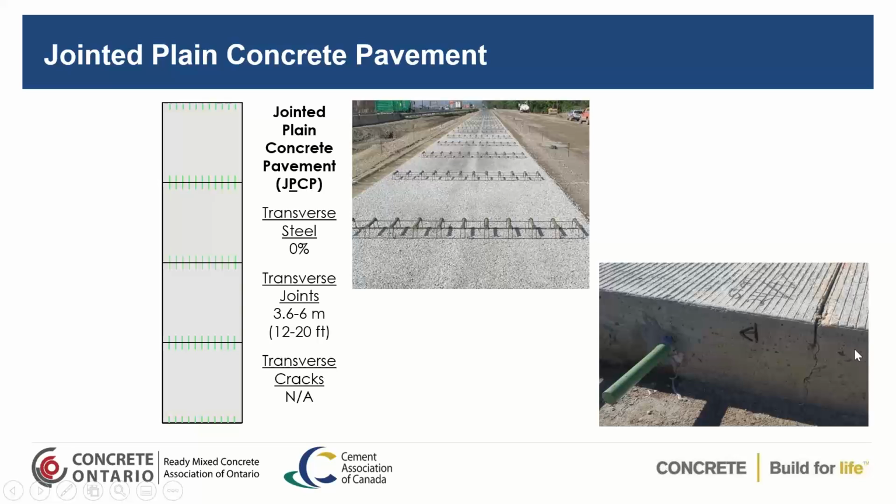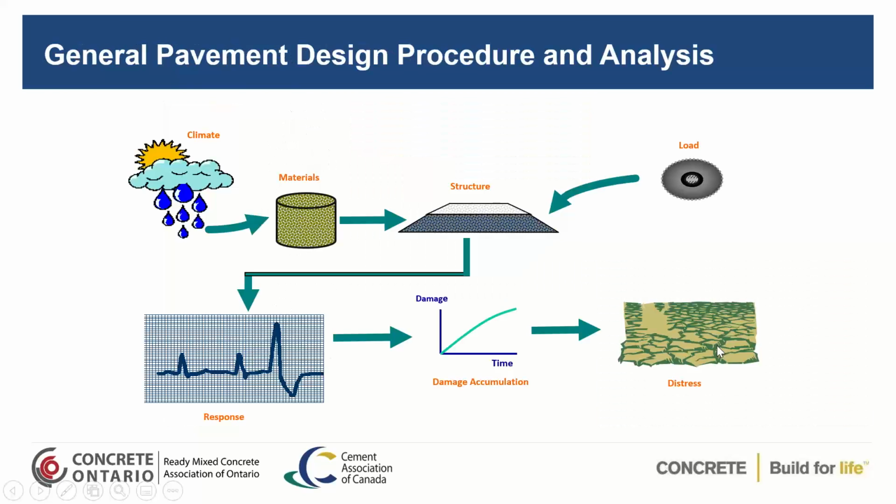This would be the end of the day transverse joint, where they've actually grouted dowel bars into the joint. You'll notice that you've got your crack down in the longitudinal, and it's down full depth, and you've actually had some dowels grouted in so that when they pour the next pour, it'll allow you to have load transfer across this construction joint.